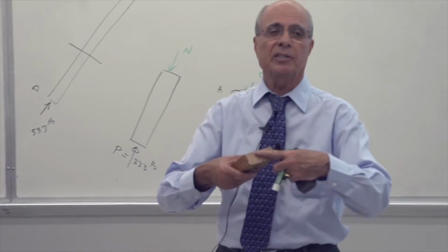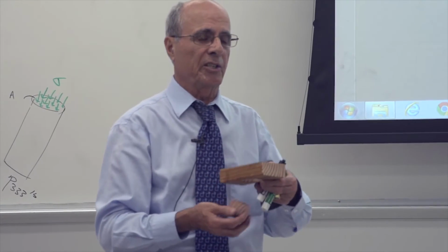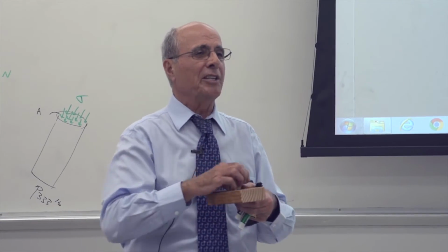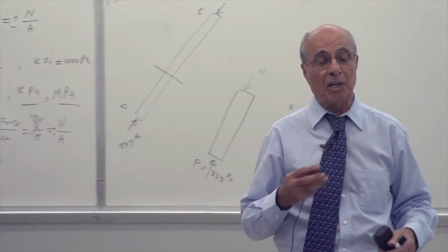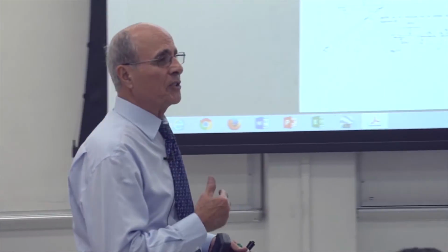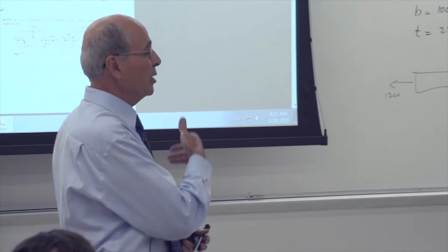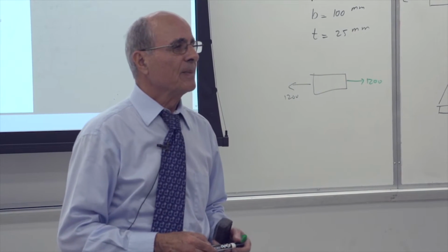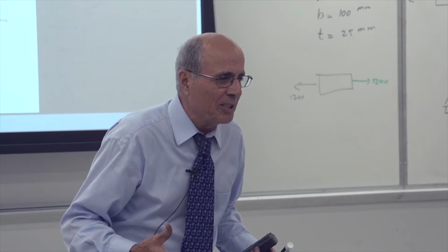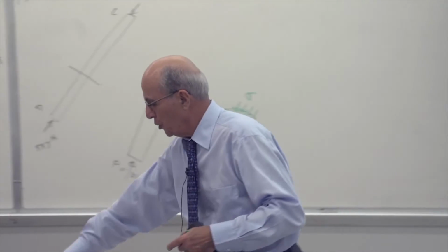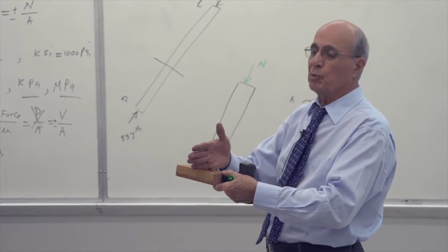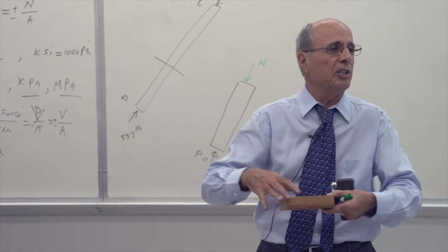Okay, first of all, my material suddenly went from this cross section, guys, everybody understand that, to this cross section. Not exactly like that. This is a very worst design. Suddenly there is a hole there. Where should I calculate? If somebody asked me find the sigma in the wood, where should I check my sigma? Should I check it like before, or check it where the hole is? Where the hole is, I have less material. Everybody understand it already. I'm making it weaker in that spot. You went from this cross section, if I cut it here, to this cross section. The hole cut the section.